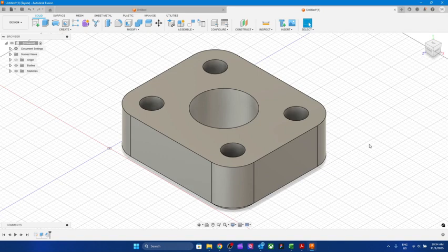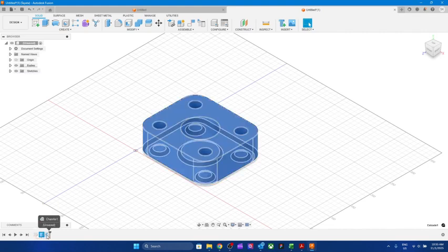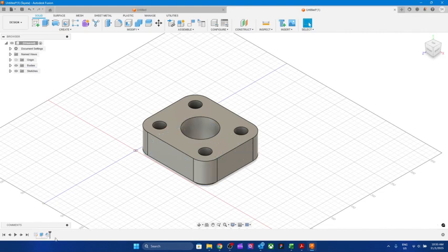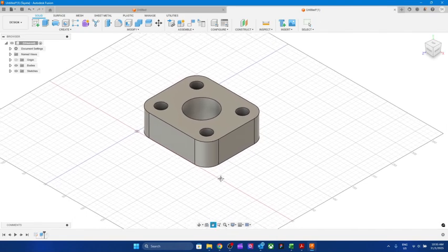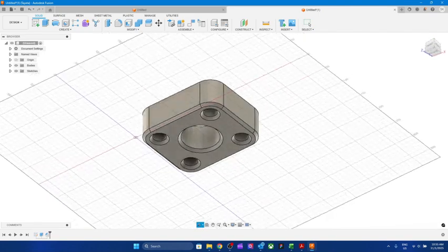Doctor, how can we edit the modifier after we've already done it? Good question. Okay, so now I want to change the size of, first of all, the height, the depth. Look what has happened. It has created the design tree. So this is my first sketch, this is the extrude that I created, and this is the chamfer that I created. So imagine I want to create something before the chamfer, I will hide the chamfer. Now I can perform the operation that I like and then unhide the chamfer again and it will be able to give me the function.